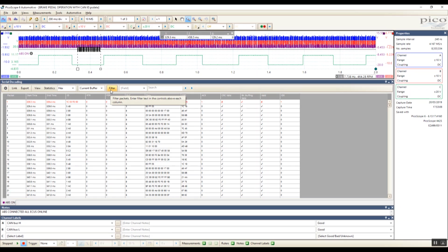But then again, that doesn't rule out the remaining IDs at this stage, because all we've done to force a confession out of these IDs, if you like, is operate the brake pedal. It could be that ID 443 that was missing will change its state if we were to spin a wheel, for example. So it's not definitive, but it's all we've got at this stage.